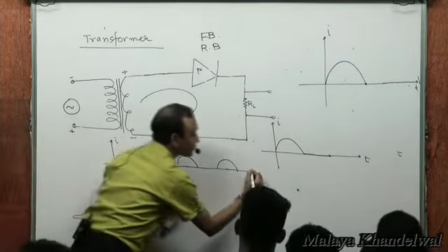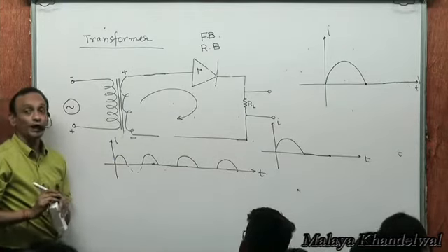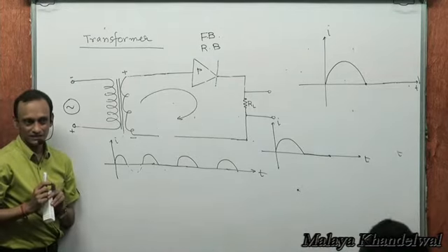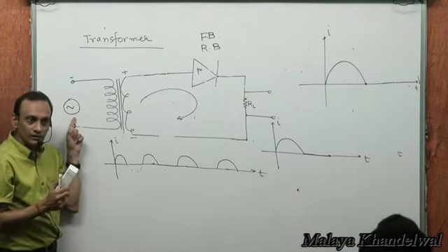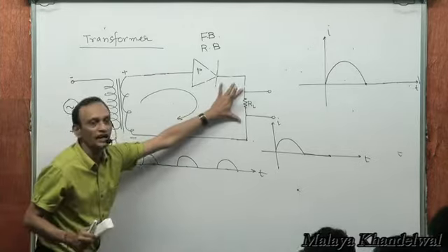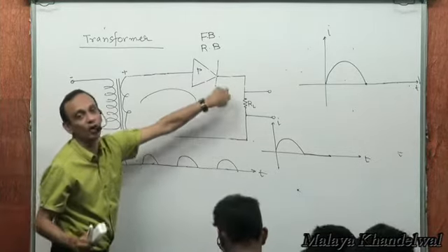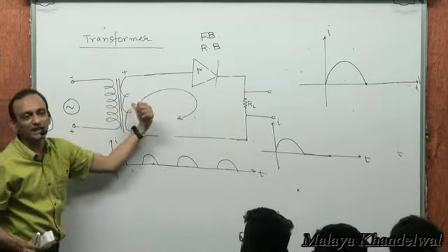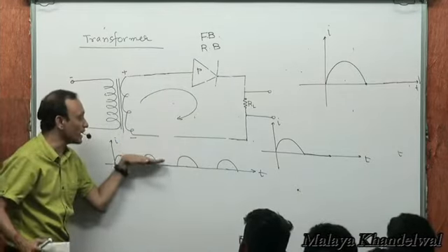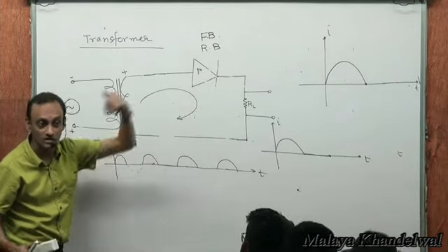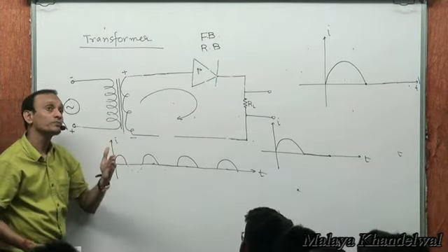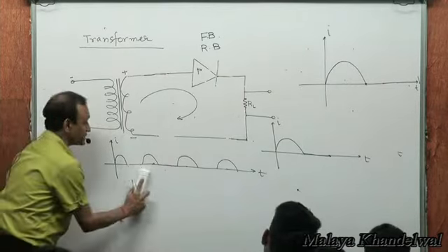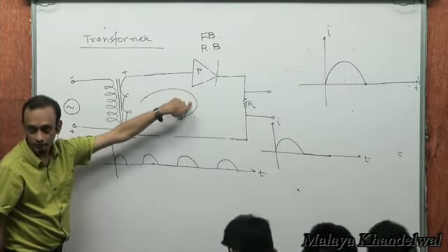Do you realize that now current is only in one direction? Even though the input signal is sinusoidal, the current through the load is only in one direction, this way. It's not in the opposite direction. Current flows only when this P-N junction in a cycle where it's forward bias. In a cycle in which it's reverse bias, it will disallow current. Then it will allow, then disallow, allow, disallow, right? So at least there is a unidirectional current that is happening through this circuit with this arrangement, right?